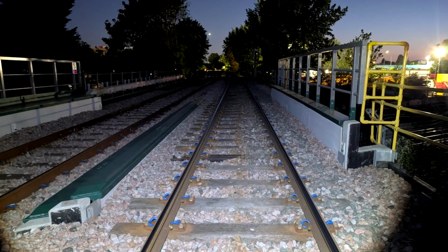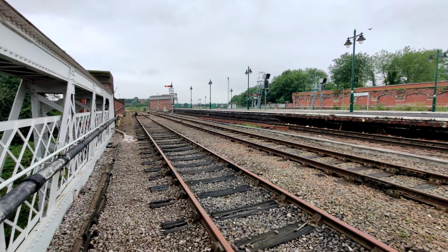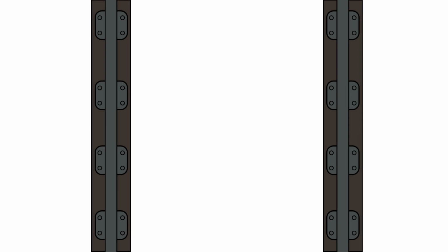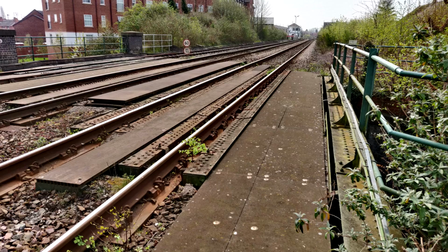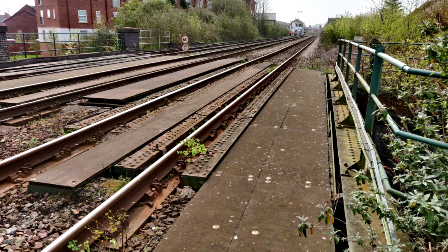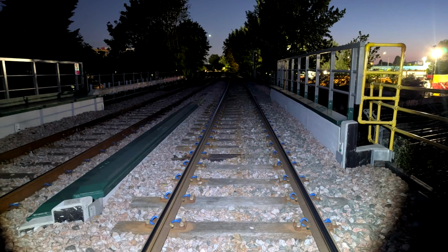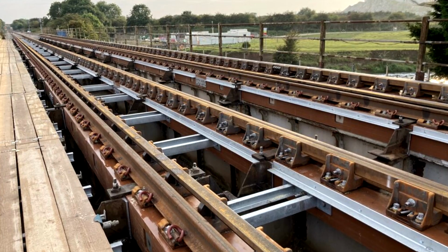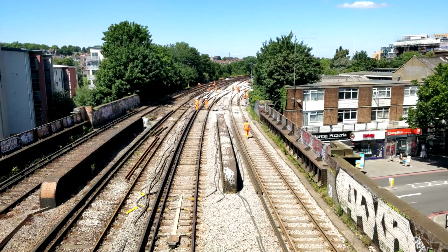Longitudinal timber bridges. These decks use long timbers running under each rail. Typical sections might be 300mm by 250mm deep. The base plates are fixed directly on top. The support width is limited. Clearance between the edge of the base plate and the timber edge can be very minimal, meaning less strength and increased risk of the timber splitting.